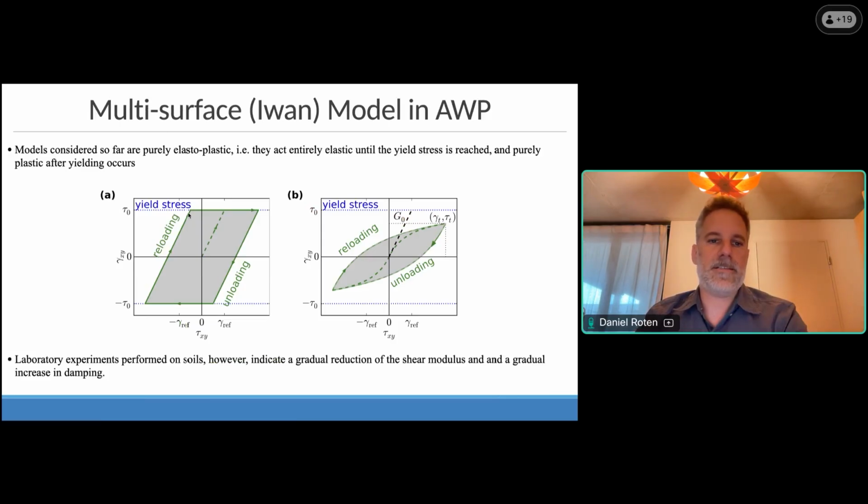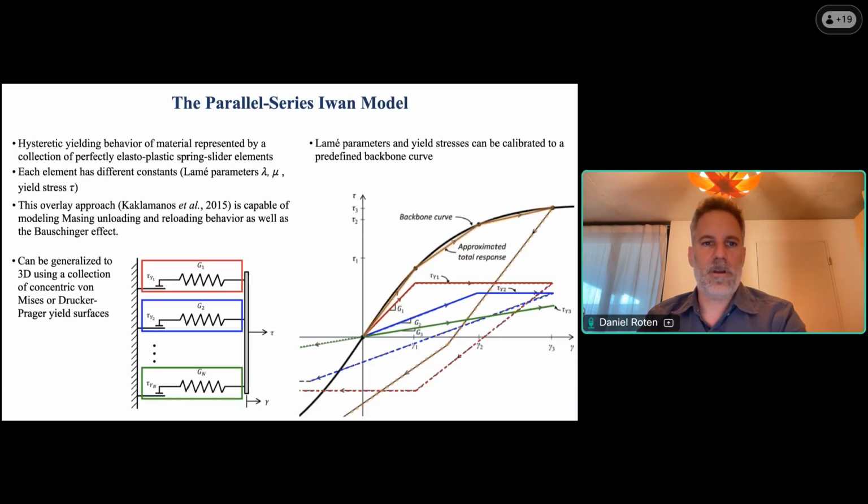In this case, we used two transition zones, so twice increasing the grid size by a factor of 3. The simulation with the discontinuous mesh only used 12,000 node hours on the system OLCF Titan, compared to almost 100,000 node hours with a uniform mesh simulation. That's a very significant performance increase. It's actually even more than that when you go to greater depth with your computational domain, which is something we often do for large earthquake simulations, where we sometimes go to 150 kilometers depth or more.